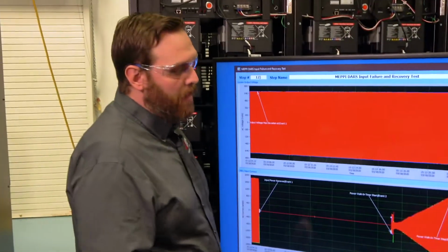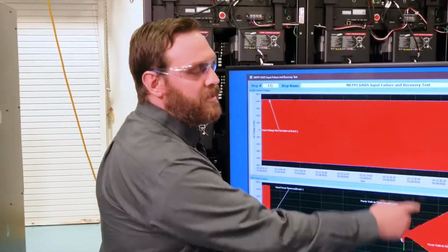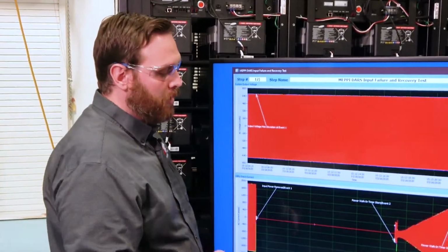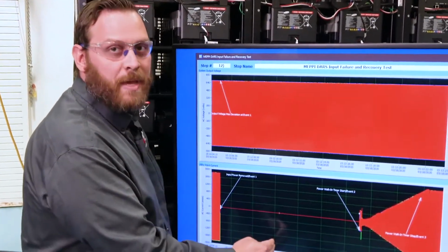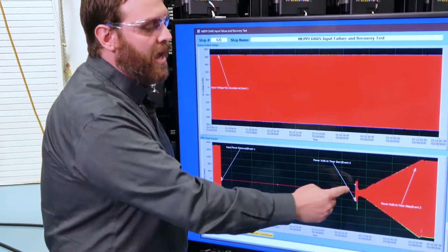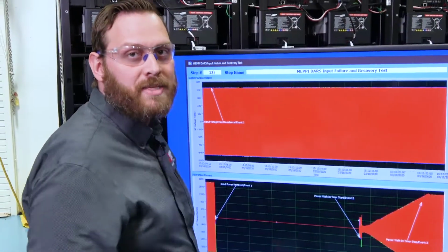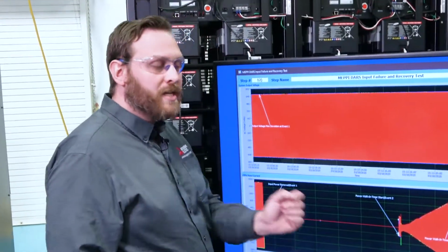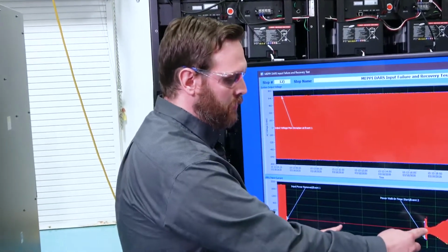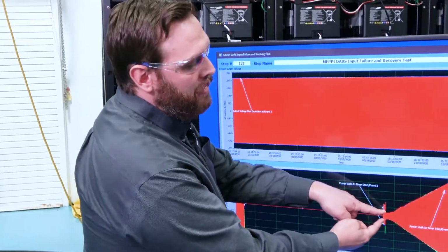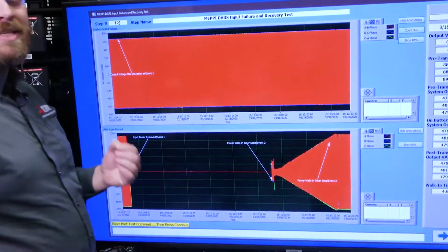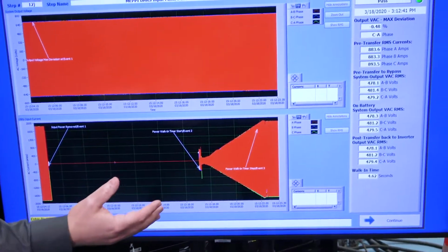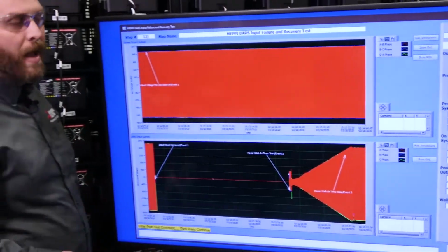The interesting thing about this is all of these time periods are adjustable. From the time period, once AC input returns, the amount of time the UPS utilizes to determine is the input source good can be set from anywhere from 0 to 3,600 seconds. The walk-in period that the UPS walks back on, you can also set from 0 up to 3,600 seconds. So changing the ramp and the time.